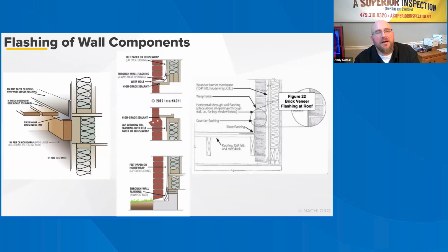Here's a good example of flashings that you should see out in the field. This one on the left is your deck ledger flashing. I continually have to talk with builders about putting a deck ledger flashing on. It is shocking to me that I still have to do this, but their frame of mind, a lot of times, is that I almost always see it on a deck with no roof.